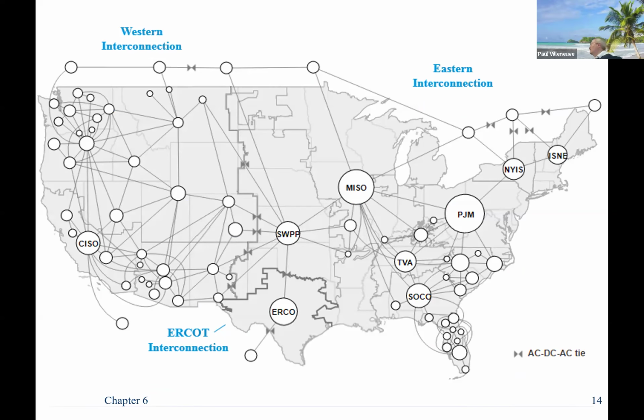And here are the balancing authorities across the US. You can see ISO New England. I guess they tried to save a letter. Same thing with New York ISO, but those are the big ones on the East Coast. Remember, Northern Maine is not considered part of ISO. You can see it goes to a circle outside of the US in New Brunswick. They have their own different ISO, but we take care of most of it. Hydro-Quebec's right in the middle of all the DC lines because they don't want to interconnect.